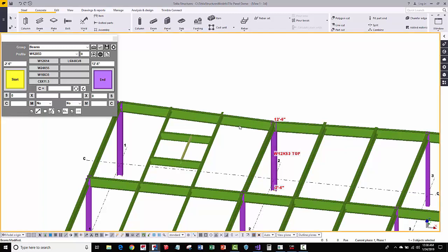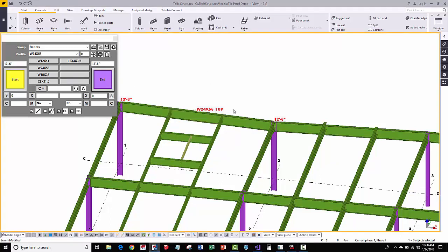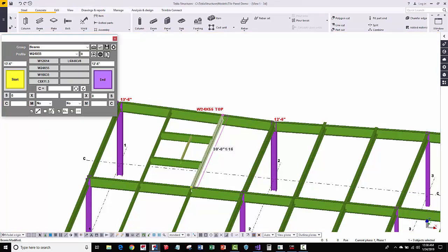Now let's say that we want the beams framing into that to also follow. So we're just going to select this beam, press Get, and then simply press the elevation modify, and it looks for any beams framing into that. And we just repeat this process. So you get the beam here so that the current properties are loaded, and then if you just press the end here, it's going to modify any of the beams that are framing into it.